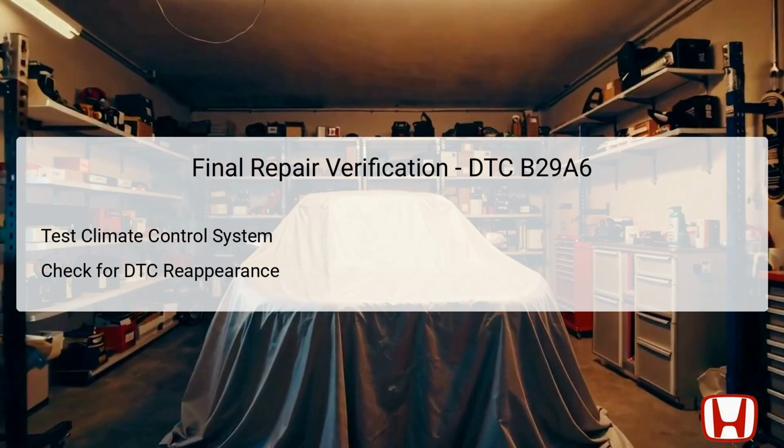This involves testing the system's operational features, such as airflow direction adjustments and temperature settings, to confirm user inputs are appropriately processed. Additionally, a thorough check for DTC reappearance must be performed using diagnostic tools. If DTC B29A6 does not return after these tests, it indicates that repairs have been successful. If the error code does reappear, this suggests that further investigation is needed, potentially indicating deeper issues within the climate control system or its components.